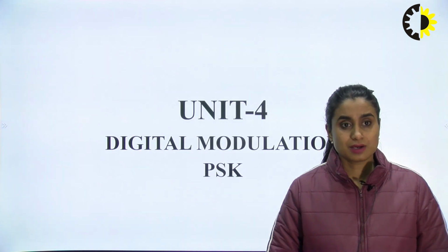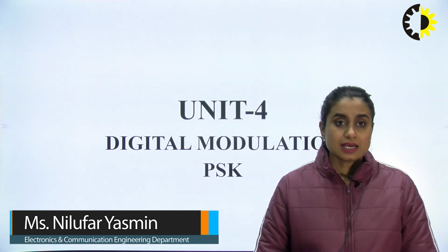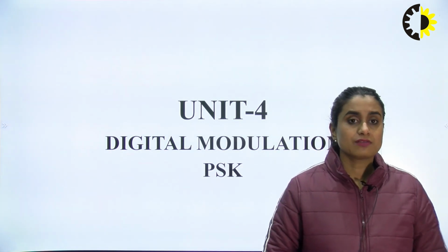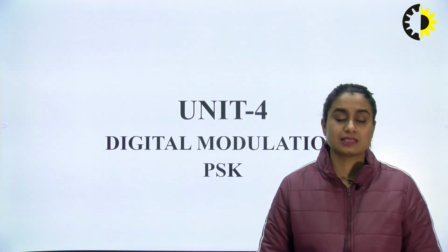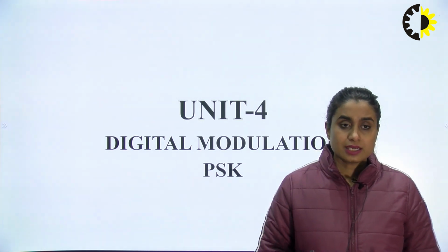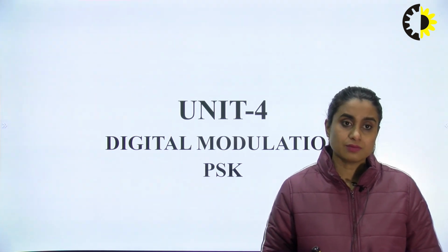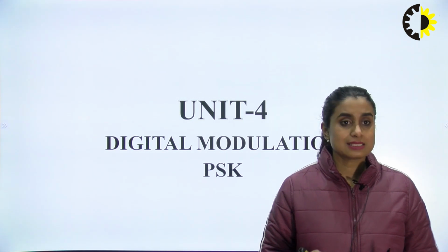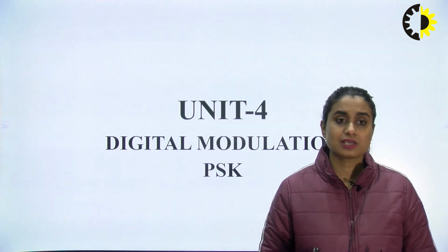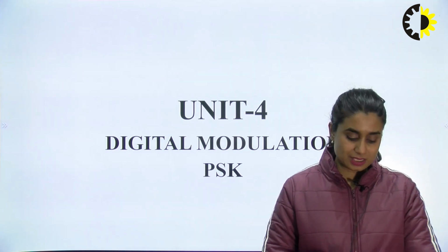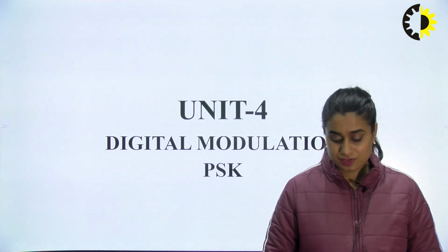Today we are going to talk about phase shift keying. We know that this is a kind of digital modulation where the phase of a very high frequency carrier wave will be altered with respect to the instantaneous value of a message signal. So here the information content will be hidden in the phase of the modulated wave. At the receiver side, when we receive the wave, we have to read the phase variations, and according to the phase variation, the actual message has to be retrieved, right? So this kind of modulation is called phase shift keying.